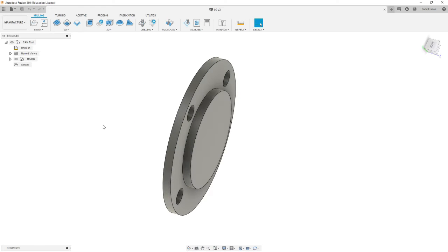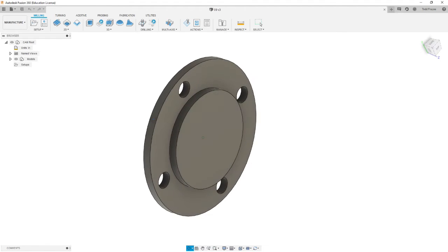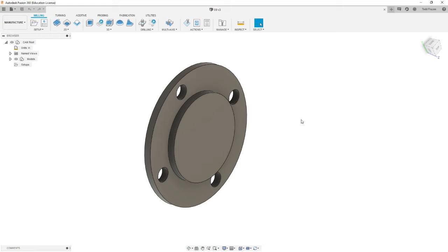Now I want to speak about one thing here. If you did not revolve your part, the lathe package is very dependent on following a linear path. Assuming you already know you're going to model the part as a turn part, you would have a sketch that could be enabled. If you don't have that, please go to the video on how to extract a section profile and resume with this video after you've completed the necessary sketch. The sketch should look like what follows.